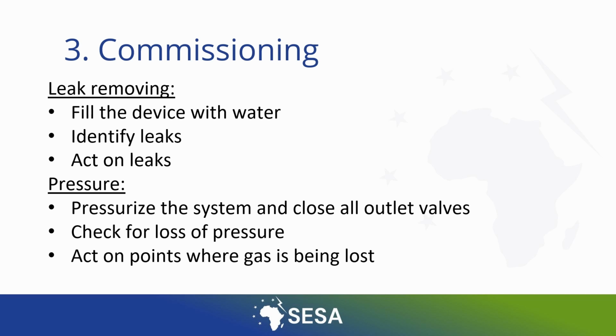Subsequently, the entire system is closed and it's checked that the manometer doesn't lose pressure for a few hours. In the event that a loss of pressure is detected, it means that there is a point where the gas escaped. To detect this point, it's necessary to apply a soapy solution to the entire gas line. If there is a leak point, bubbles will form revealing the leak point. Once located, it's necessary to act on this point by applying insulating and sealing materials.